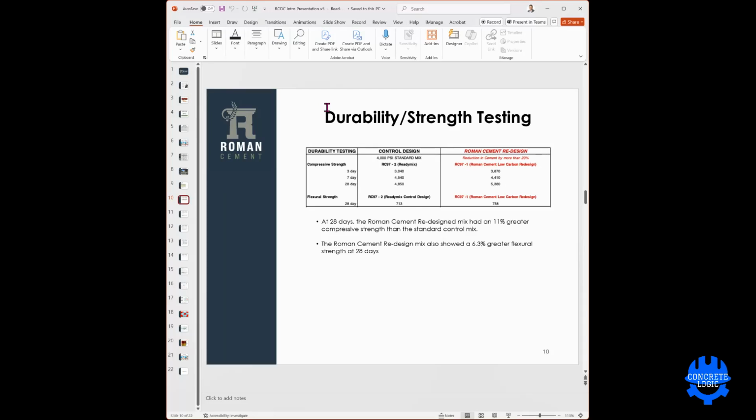So it creates an ideal situation where they could blend it at the back end. The result would be a cement that has more limestone powder than the cement it's replacing. So when used at a batch plant, they would have to use a little more of that blended cement than they would use currently, and make some adjustments to the water and the admixtures. But that's a way in which a cement company could actually implement this technology.